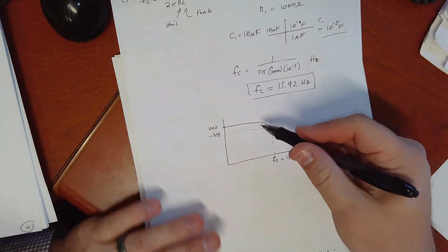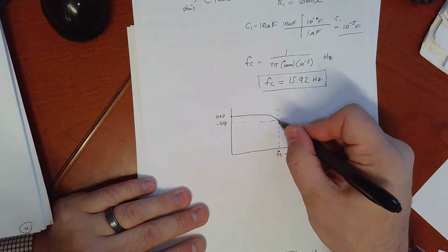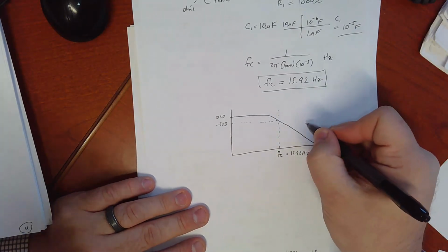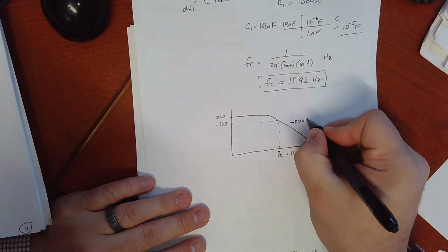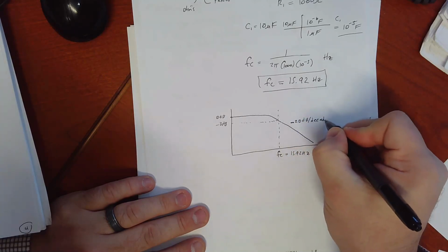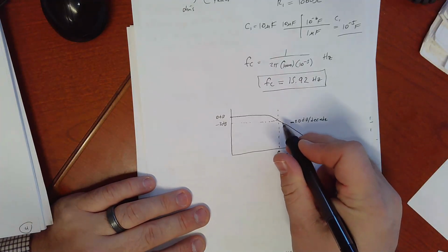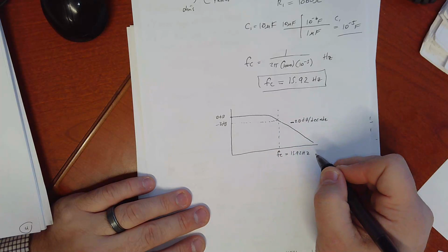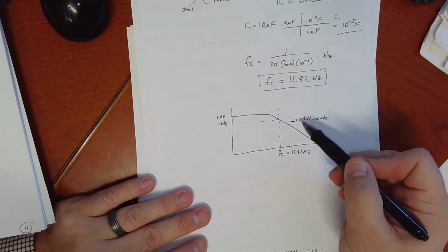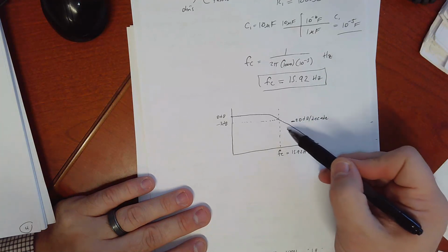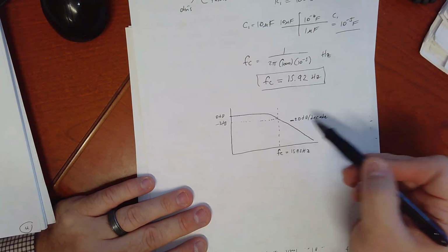So you've got a gain of 0 decibels or 1. And then it'll start to fade off. Here's our cutoff frequency. And then this is going to go down at minus 20 decibels per decade. So for every increase of a decade of frequency, you'll drop by 20 decibels. That's the slope of this line. And with higher order filters we'll learn we can do some fancy stuff where we can make this steeper, because if you have another signal close by, you may want to block it more effectively. This may not be a steep enough hill.